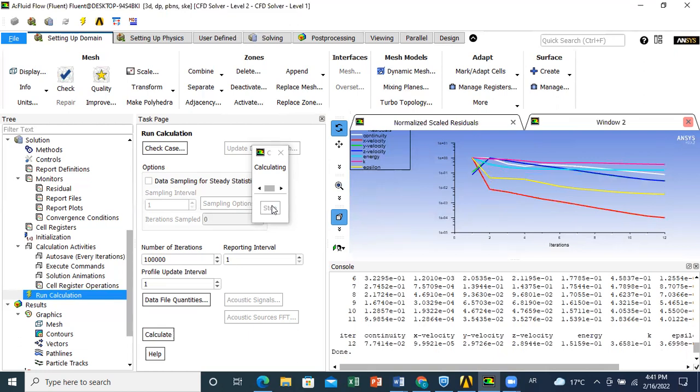So now we can go to graphs. You can try to see what is the state of your solution. You can observe, let's say, the temperature field and velocity field, to see what stage we reached in our solution. In the contours, you can explore graphs for your different variables. You can see your temperature graphs and your velocity contours.